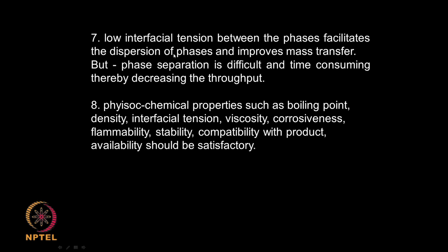Low interfacial tension between the phases, then dispersion of phases is good, mass transfer is good, but when interfacial tension is low, the phase separation becomes difficult. So, it takes much longer time for the phases to separate.